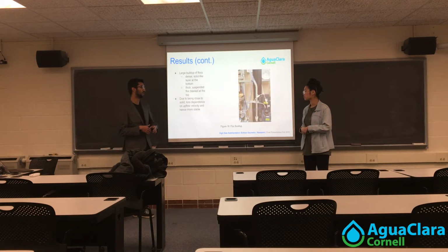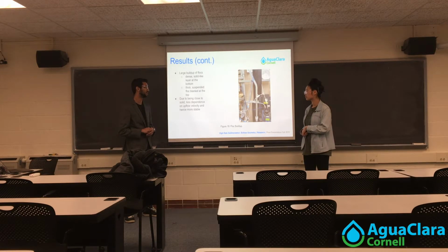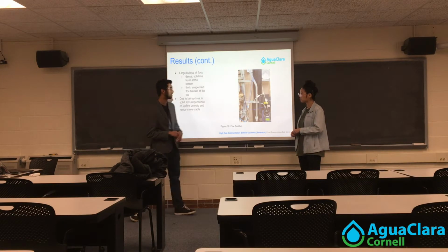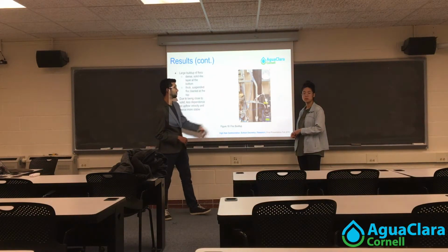So once we had run the experiment comparing the flocculators, and we know it's no longer attributed to the flocculator, we decided to see what actually was going on in the sedimentation tank. As in previous experiments, we either ran out of clay or coagulant before we got back into the lab, and hence never really got to see what was occurring in the sedimentation tank. After running the experiment and coming in after 24 hours to see what was going on, we noticed that there was really dense buildup of flocks at the bottom.